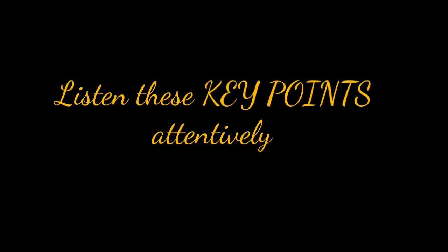Now I am going to take some important key points from week 10, so you have to listen to them very carefully. Batteries help in moderating the difference between demand and supply across the day by storing and releasing energy as required. And electrode reactions that occur during discharge are reversed during recharging in a secondary battery. And in the standard electrochemical series, the potential corresponding to the hydrogen electrode is set to 0 volt arbitrarily. And lithium metal was used as the anode in early versions of rechargeable lithium based batteries.